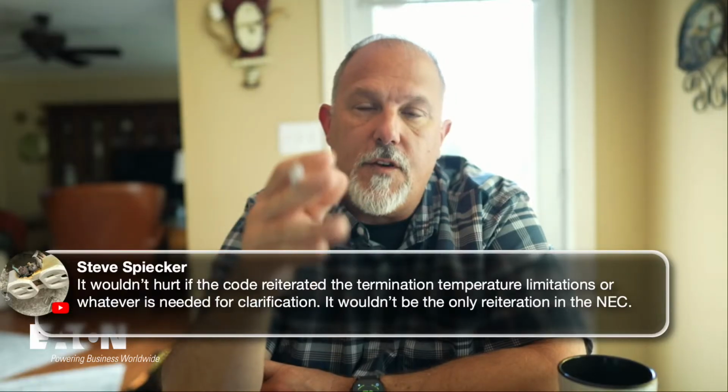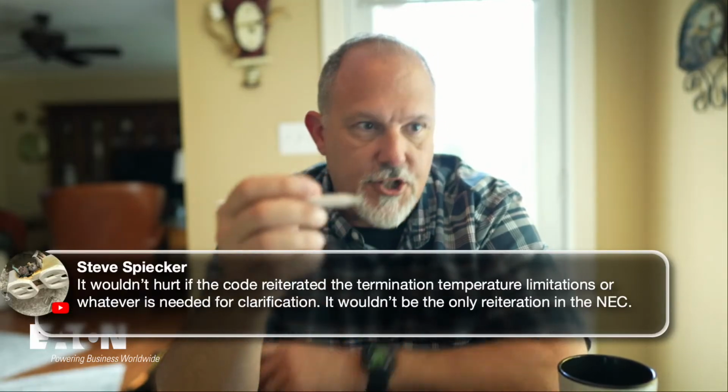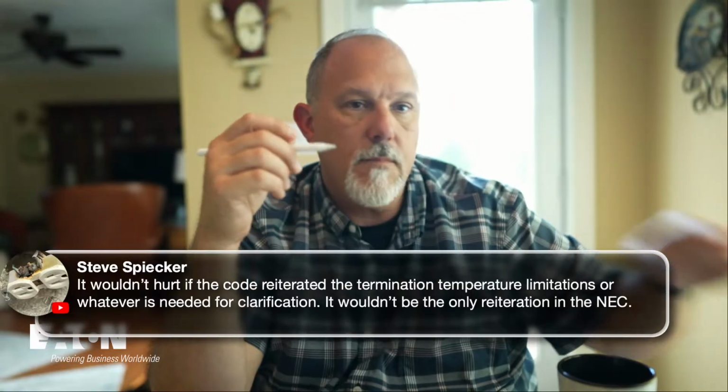And we know from 240 and our discussion earlier that I can go to the next larger if I'm using a circuit breaker where my overload protection is a part of the circuit breaker. I could go to the next larger overcurrent protective device when it doesn't equal a standard branch circuit overcurrent device ampere rating, based on Article 240, 240.6, I think it is.